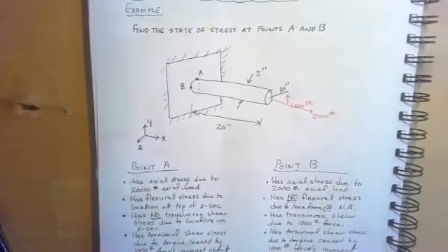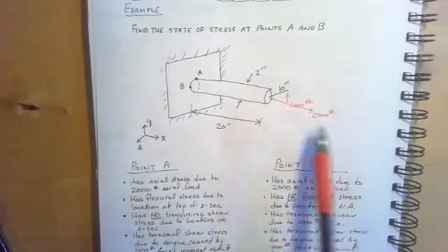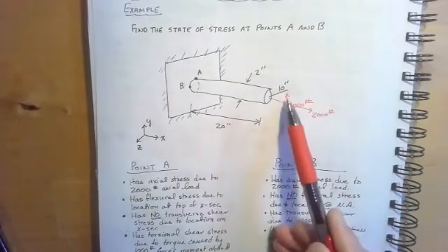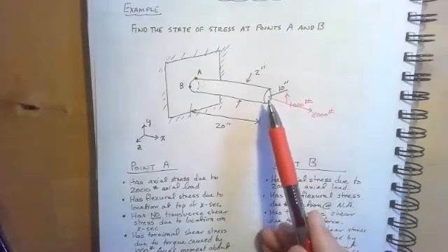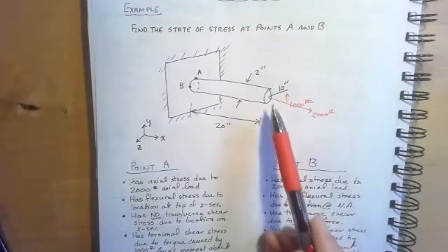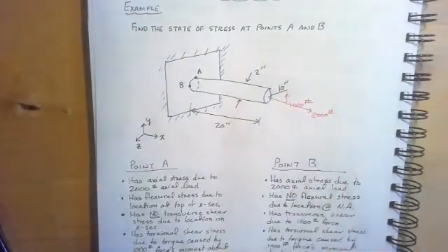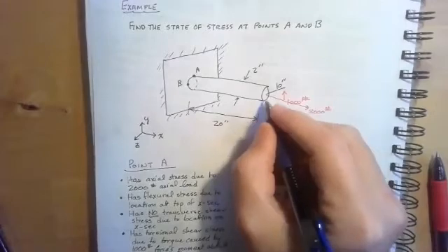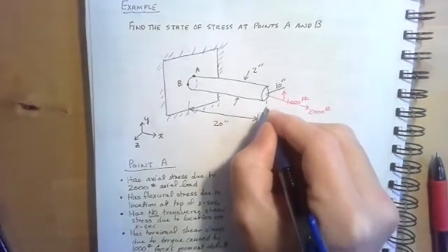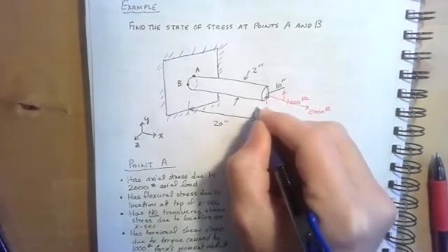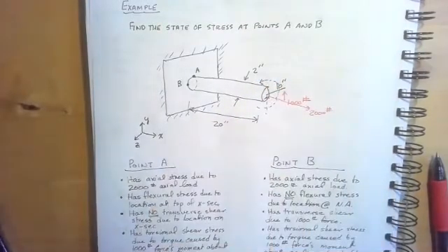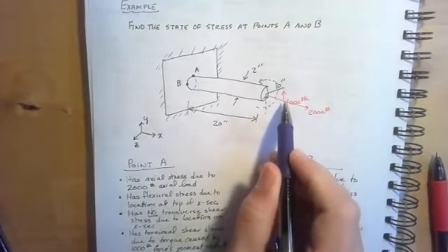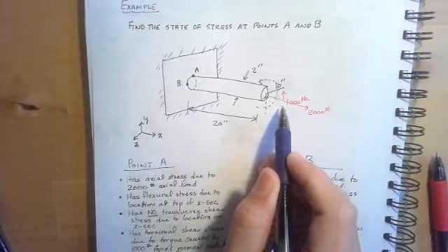So we've got on our shaft here a 2,000-pound tension, and I've got a 1,000-pound force applied with an eccentricity of 10 inches about the center of the shaft. So it's got a force component and a moment component, and we can think about this particular force being replaced by an equivalent force couple system. I'm going to just show these in dashes because they're the same thing together as this 1,000 pound force.